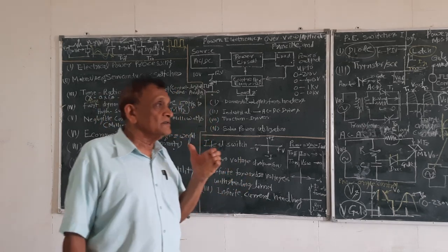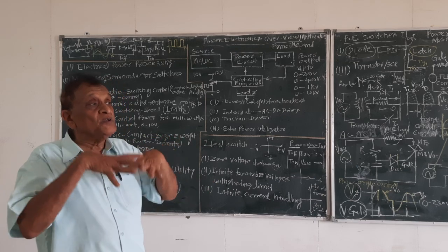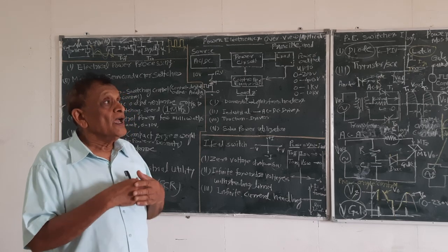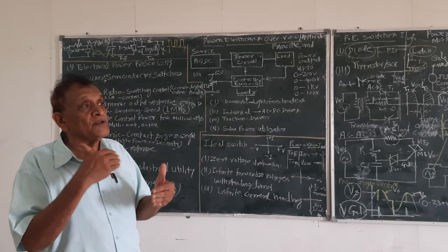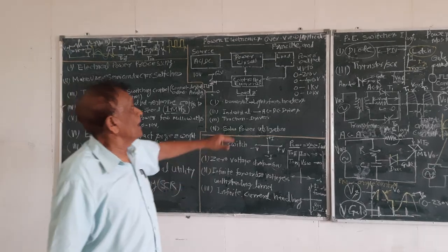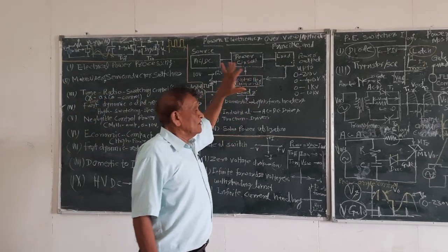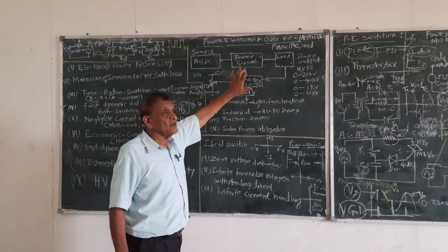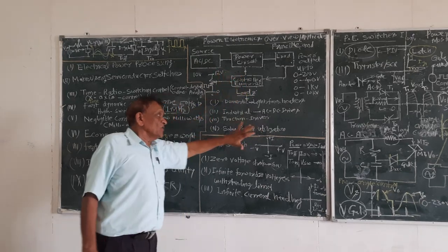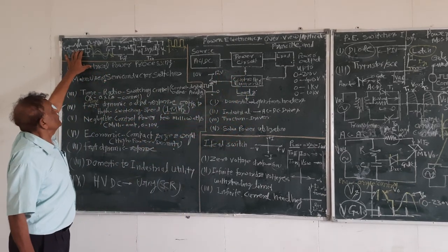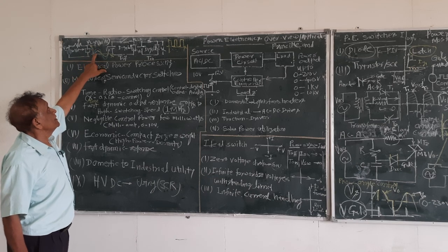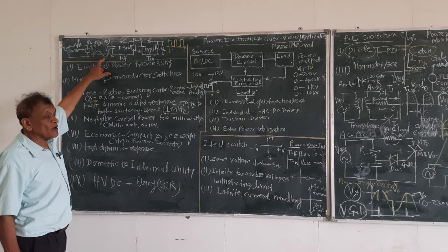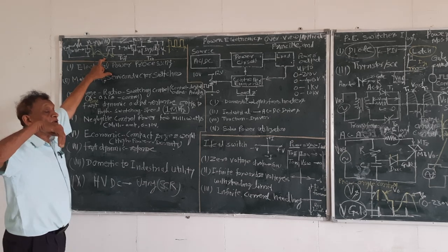These are the devices which are used as switches, and a switch consumes less power. Therefore we can obtain any form of AC or DC supply voltage required by the load with the help of these, with very little input power and almost zero, or negligible, power loss in conversion. If you are using a rheostat in place of switches, then what will you get? You will get power control, but there will be enormous loss, with very low efficiency and more losses.